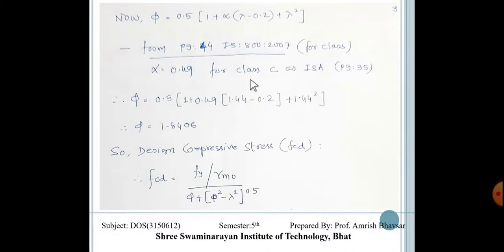Once we get the class, from that class we will take this value of alpha as 0.49, which is given on page number 35. So alpha for the class C is 0.49. We have to put this value in this equation. So after putting all the values, we have alpha, we have lambda, all the things we have. So we will get phi, that is 1.84.